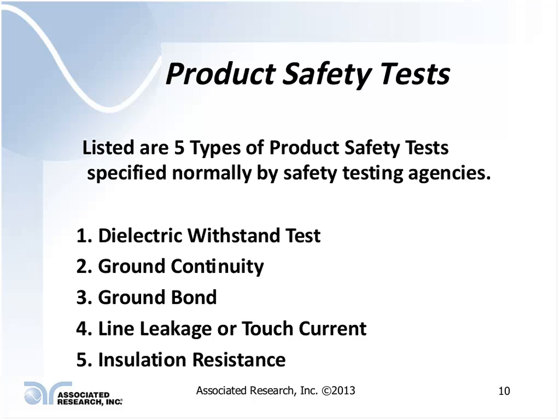Okay. If you look at the specifications for a ground bond test and relate that to the fuse rating or circuit breaker rating of the product, you'll find that they're very, very close. Time delay fuses or circuit breakers are typically designed to carry a 200% overload for 2 minutes.